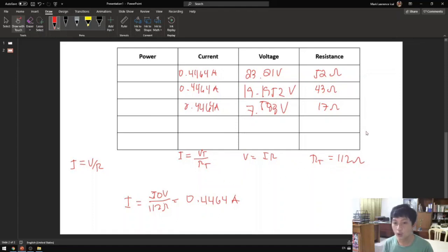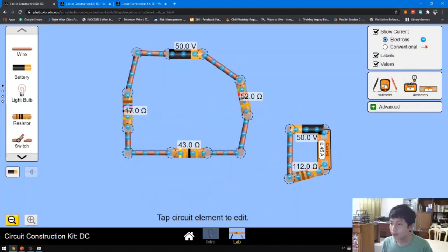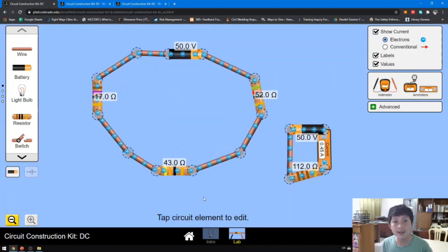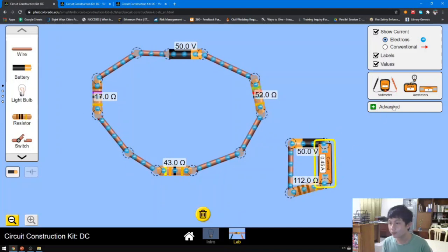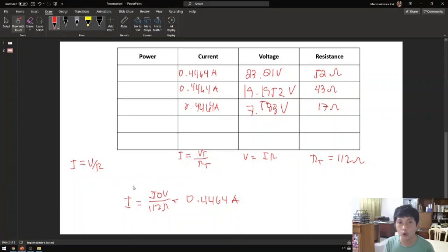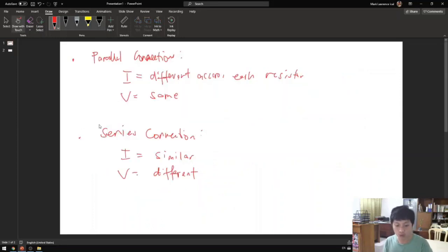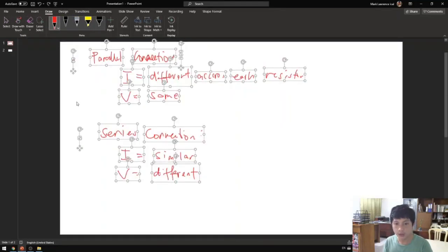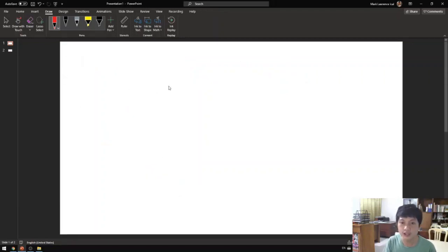How about the power? As I told you, since they have different resistance and different currents, they have different powers. However, if you combine them, you practically have the same thing here. Now the power is given in terms of Joule's law. A while ago we talked about Ohm's law, now we're talking about Joule's law. Now Joule's law is like this.